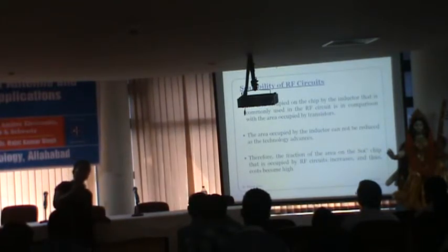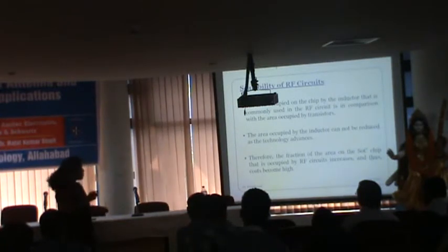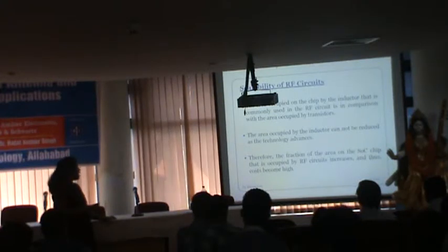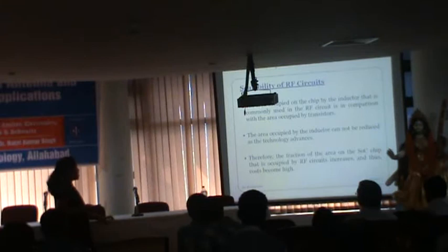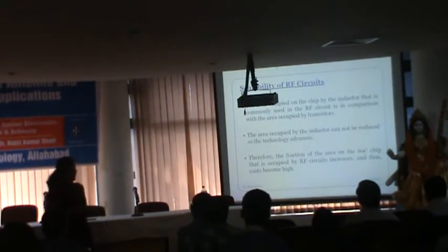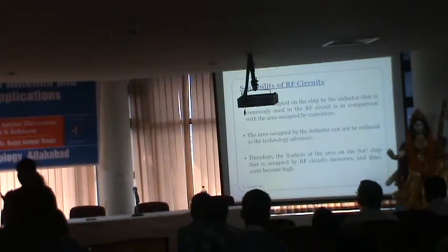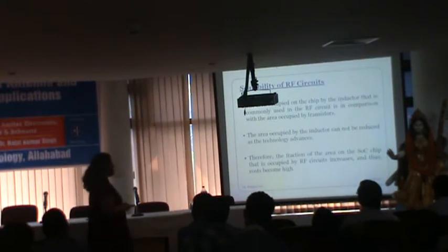When you are talking about the technology advancing, it means you are reducing the feature size of the transistor, right? But you are not actually reducing the size of the inductor. So that is another challenge. Now, therefore, the fraction of the area of the SoC chip that is occupied by the RF circuits, including inductors, increases, and thus the cost becomes very high.